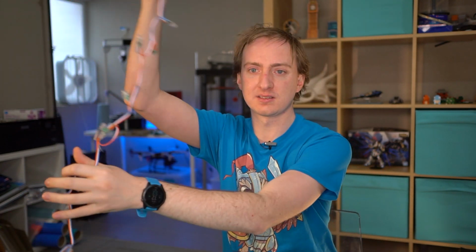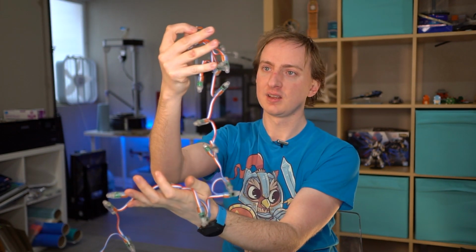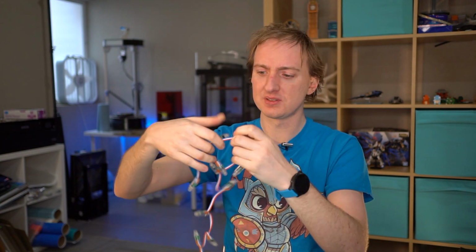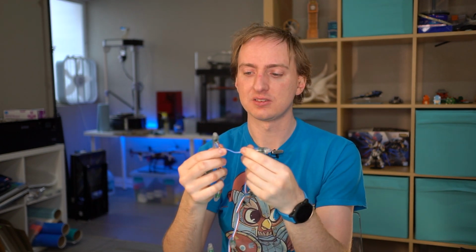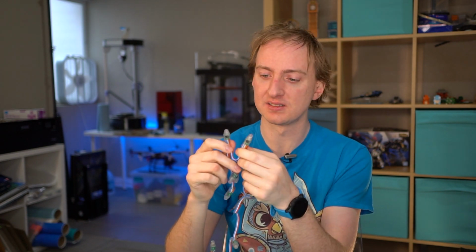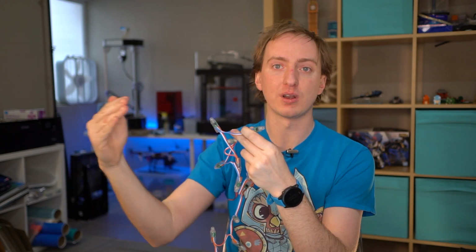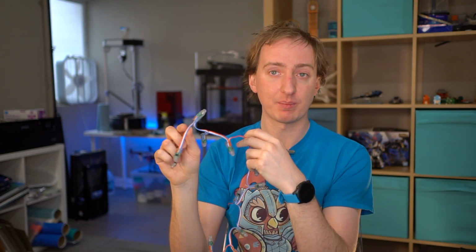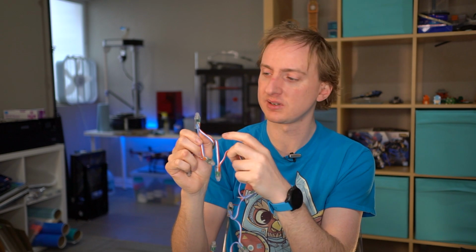And then for the actual lights, what I'm going to use is addressable RGB LEDs. Now, sometimes you may have seen them looking like this. This is a string of them right here. And the way these work, if you can see, there are 3 wires. And what you can do is you can have not an infinitely long, but a very long string of these LEDs, and each of them has an address, basically one on from the previous one. So rather than having to have a pair of wires per LED to change what color it is, instead you've basically got a power, a ground, and a data line, and then you can just send instructions down and have the entire chain light up different colors.